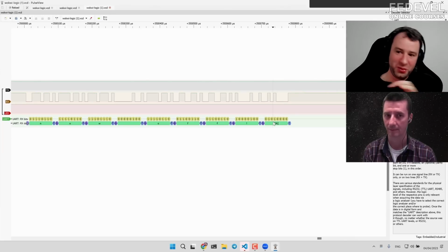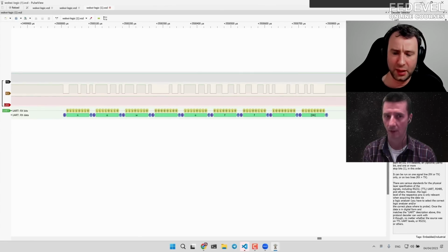So I'm actually using this very method to debug the simulator itself, to make sure that we simulate the protocols correctly. I think the SD card was, for instance, very challenging. If you run a simulation with the SD card and connect it to this virtual logic analyzer, you can see there is tons of data being sent back and forth. Without tools like this, it would have been a nightmare to debug. There are millions of edges on the signals that you have to take into account. And if you don't have those decoders where you can actually see the data, it's just a big headache.